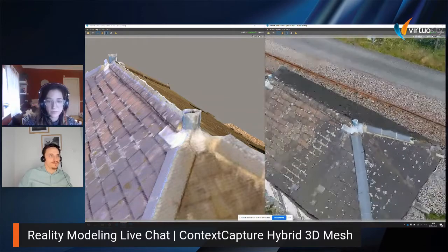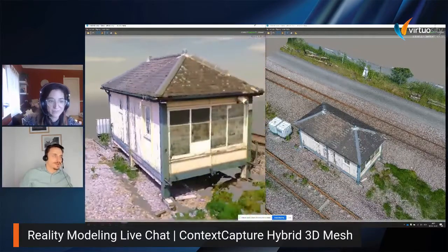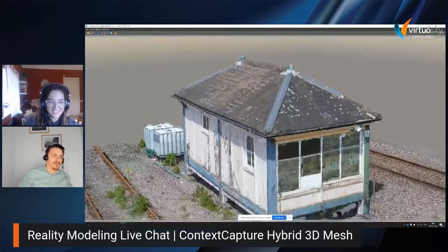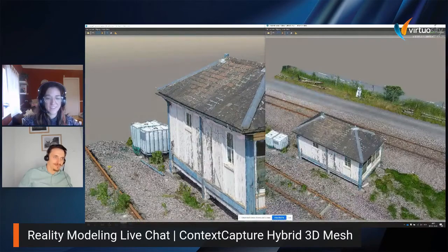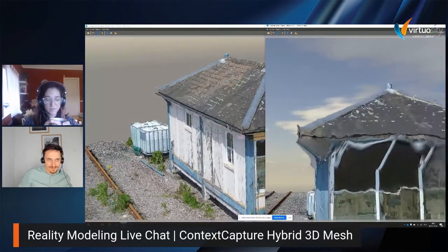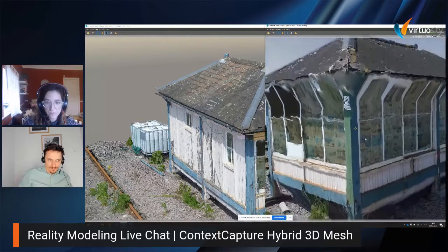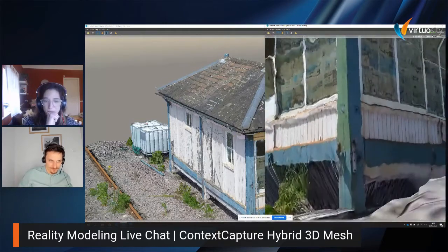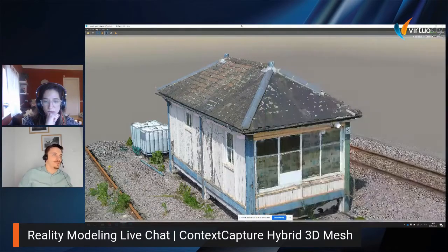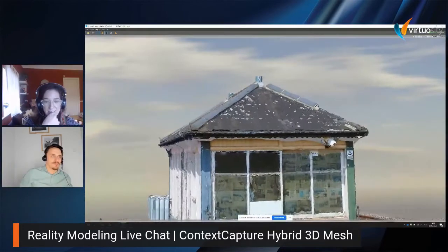But what about the idea of merging those two together, which is possible? Then we are going to the last step. We can merge them like here. Photogrammetry has another disadvantage of changing the shapes if it does not get full coverage, as you see. So we are missing some information from, for example, below the building, below the roof. But if we merge those two together, then you get the best of both data sets, the best of both sources.